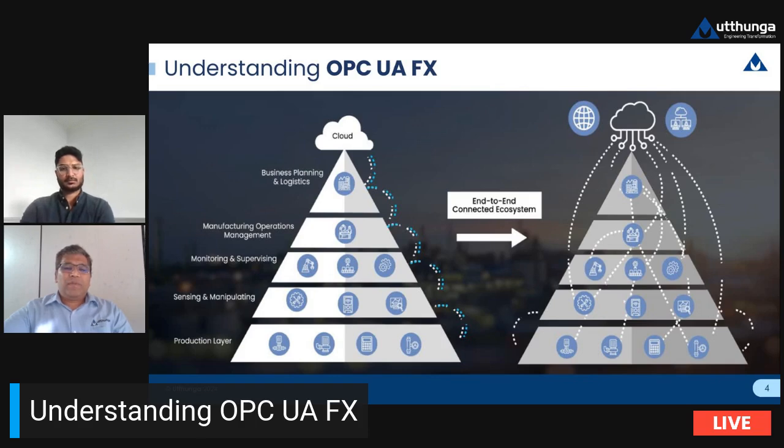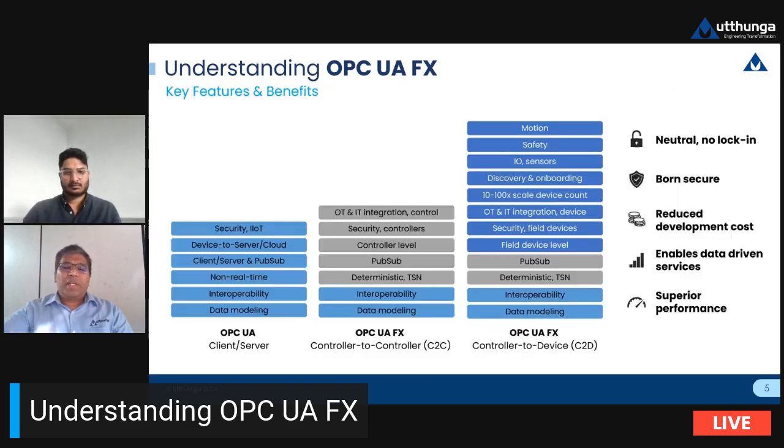So, with this flexibility and this scalability, it is easy for you to have OPC UA vertically in any of the layers as well, moving away from where OPC UA used to operate in a traditional manner. So again, OPC UA has different technologies within it, the client server and then the pub/sub over MQTT and AMQP. These technologies enable building a connected ecosystem in the upper layers, whereas